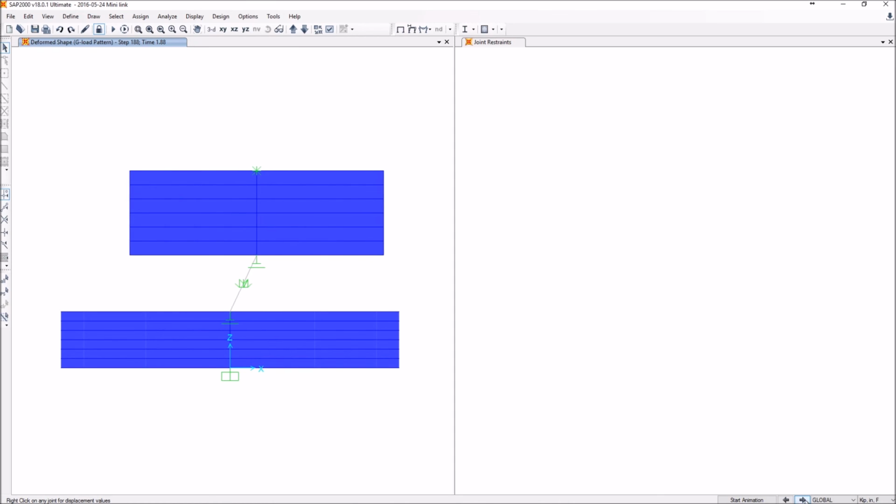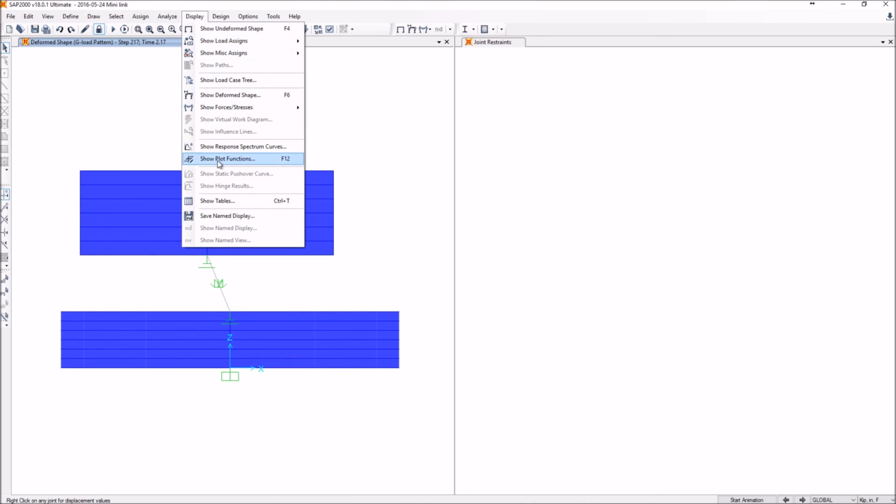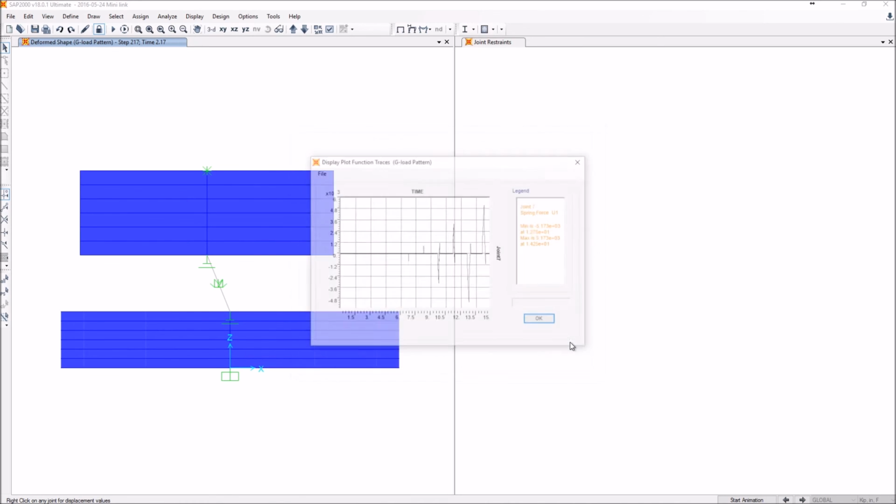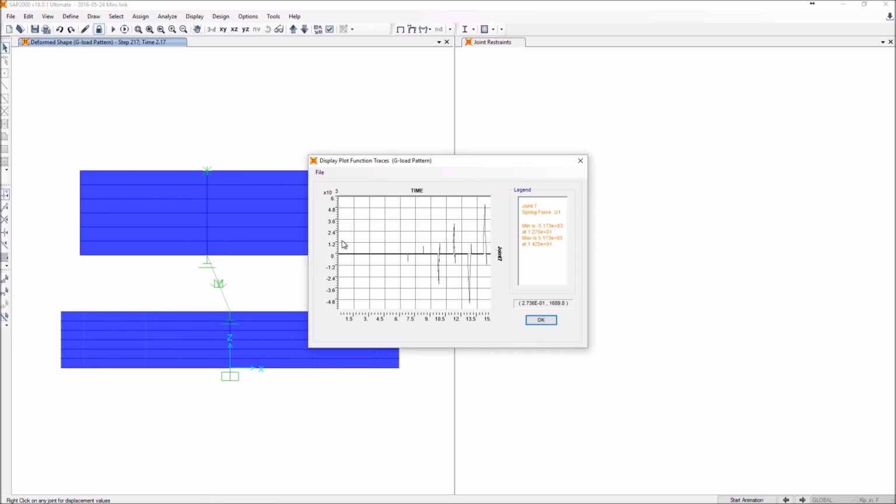There's no jumping in my ANSYS solution. Everything is smooth, the transitions are smooth, but here in SAP we see this jittery back-and-forth effect that's captured in our output. When we look at the display, at first it's very difficult to tell, but when we zoom in, for the first 6 seconds we don't notice any of those spikes.